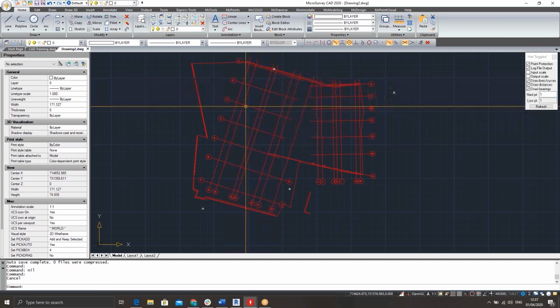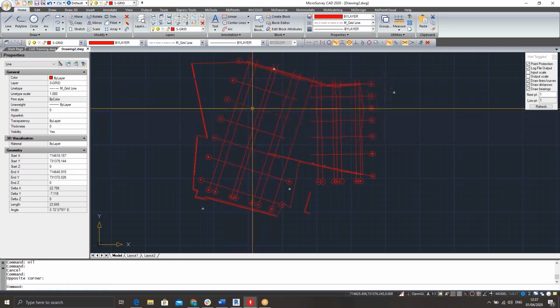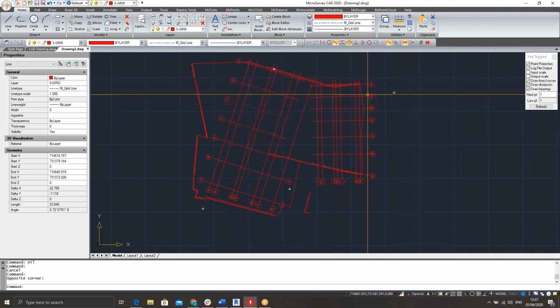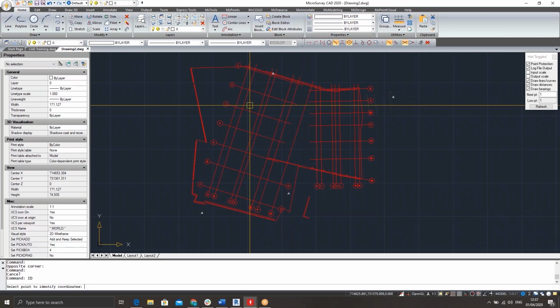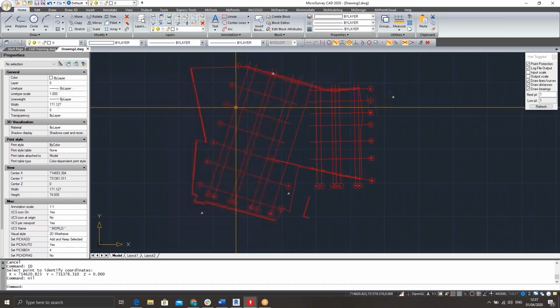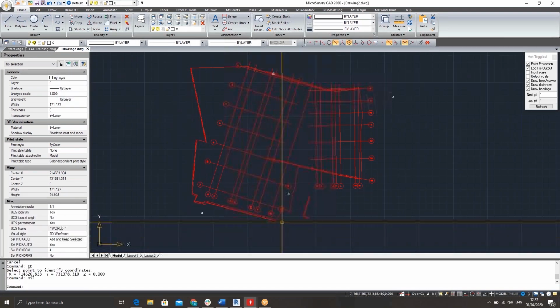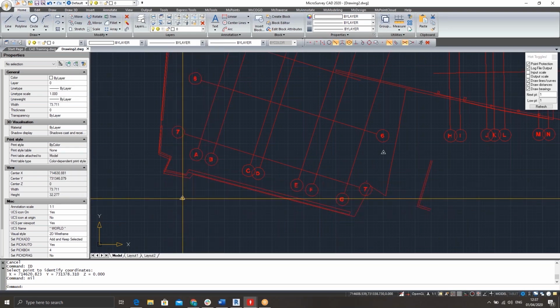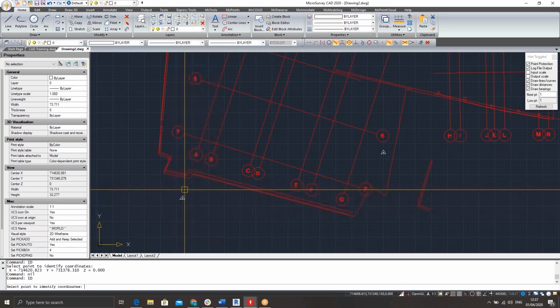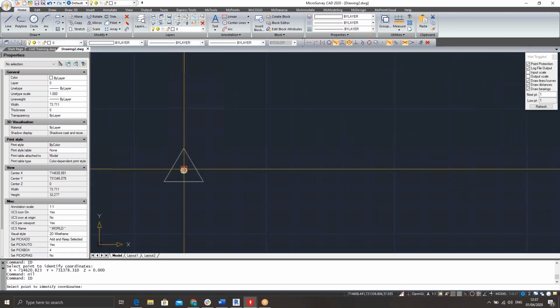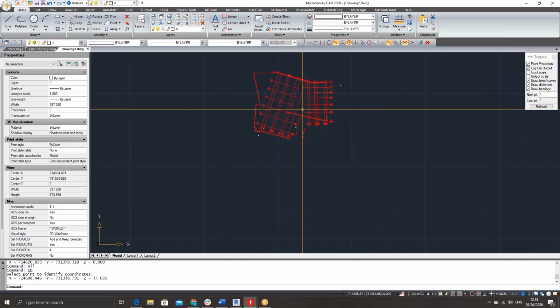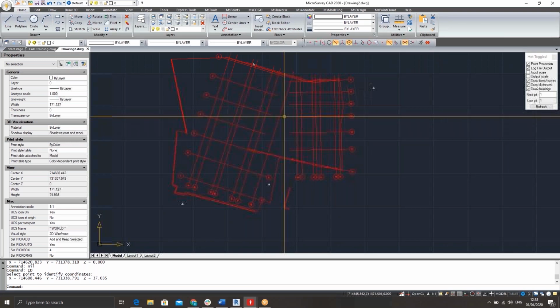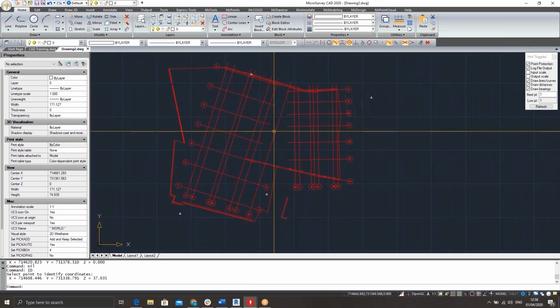Once we're happy with that, and again, I like to double check, triple check, so I'll select an element, maybe select a couple of elements just to make sure that the individual points actually highlight. And then I'll double check ID, as it could be a case that we know what the coordinates of these control points are. So it's never a bad idea to jump in again, just checking those coordinates against what you know them to be. Once you're happy that your drawing is cleaned up, you're ready for export.